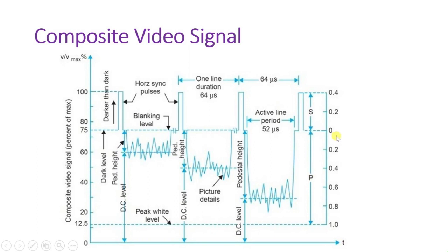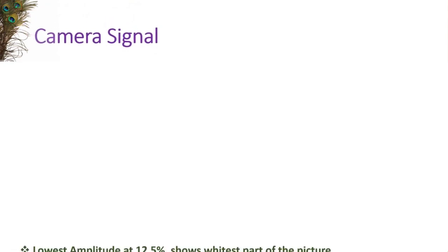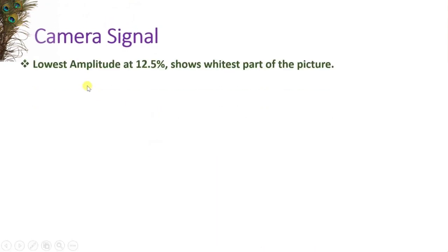Superimposed on top of the H blanking pulses are the narrower H sync pulses. As shown in Figure 7.6, each sync pulse is 0.08 H, or half the average width of the blanking pulse. So this sync time is approximately 10 microseconds divided by 2, or 5 microseconds. Front and back porches. During the remaining half of the blanking time, which is also 5 microseconds, the signal is at the blanking level.